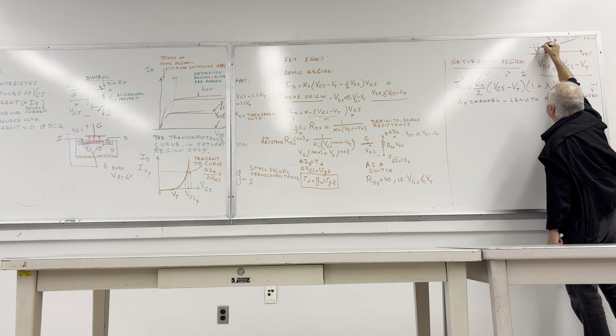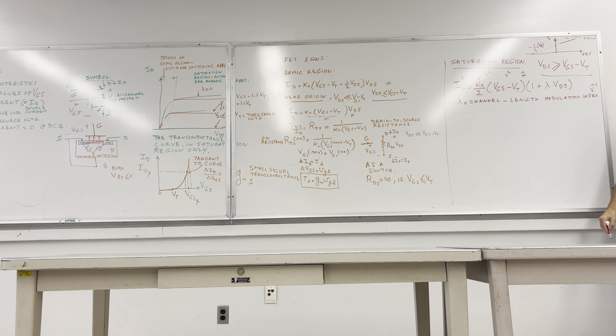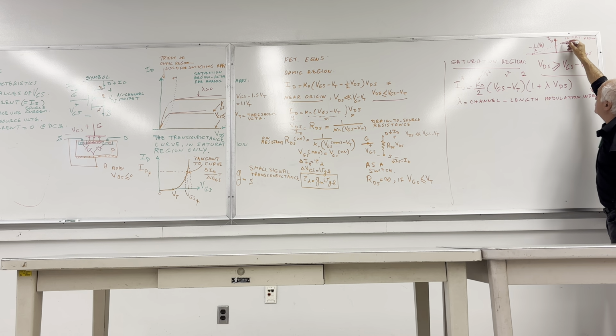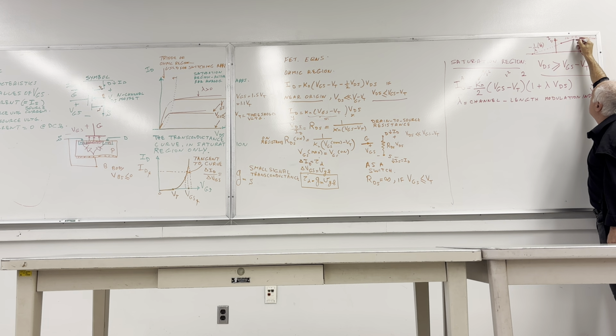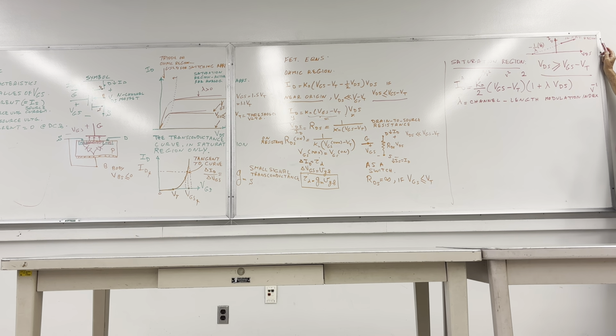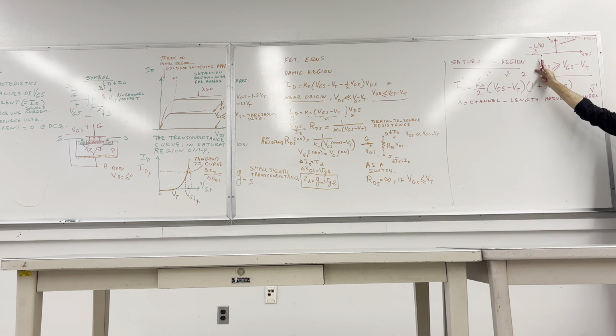It is analogous to VA, early voltage in the transistors. So experimentation is easy. Go get the characteristic, ID against the VDS. Get 2 points on the line in the saturation region, extrapolate that line. Wherever it cuts, figure the voltage, flip that voltage, and that is your lambda.